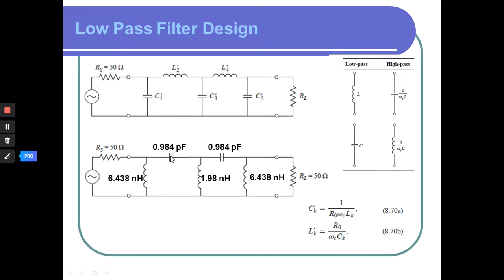And for anything capacitor, which you already converted from the prototype, you need to use this value. So again, I'm telling you, first you need to declare yourself a prototype of low pass filter for the high pass filter, but you don't need to calculate these values. From here, you need to convert according to this table.